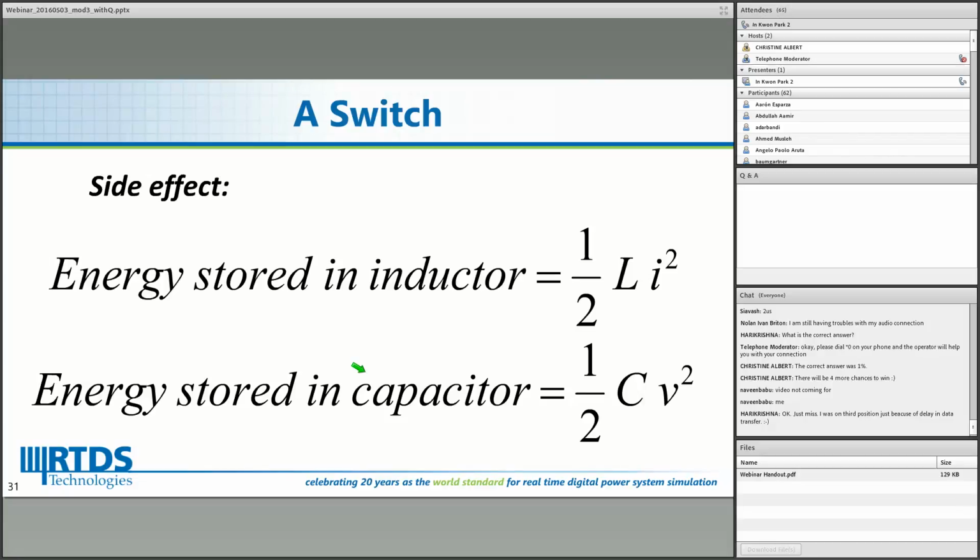So this is purely fictitious, only happening in your simulation. As long as your switching frequency is low, you can probably live with a small amount of fictitious loss in your circuit, but if you raise your switching frequency, then the fictitious loss begins to show up in your simulation result.